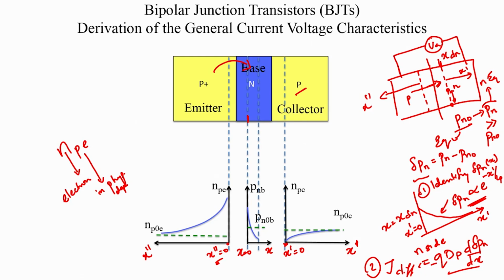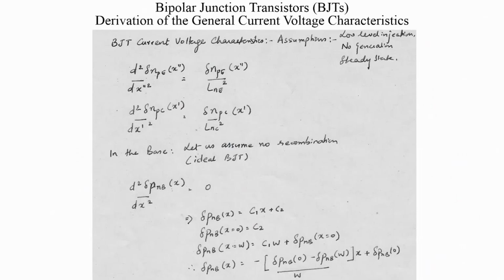We are going to treat these 3 independently and bring in the effective impact of these 3 solutions at the last step. So we have these 3 coordinate systems and the concentration profiles of the minority carriers. Here I have just qualitatively sketched the profile, but if you want the exact mathematical variation of the profile, you want to be solving the continuity equation for these 3 regions.